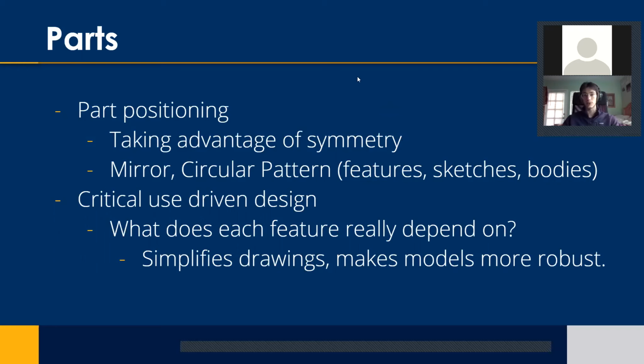When you create a part, there are 3 fundamental planes that are given to you. There's the top plane, the right plane, and the front plane. If you design your part so that it's centered among those planes, then you can use symmetry to your advantage when designing the part. For example, if you had a mirror image of a complex part, you don't have to do all of the steps for both sides. You could just do them on one side, then mirror all of the features from one side onto the other. That'll save a lot of time. This also works for circular pattern. If you have a complex circular part with lots of rotational symmetry, you can just make one portion of it and then copy it around in a circle.